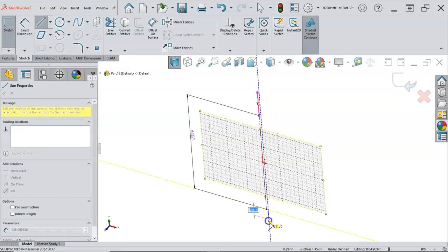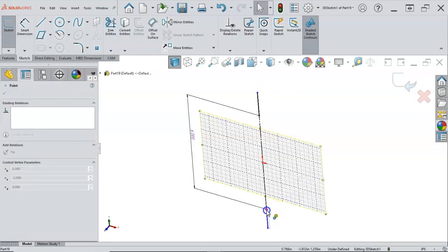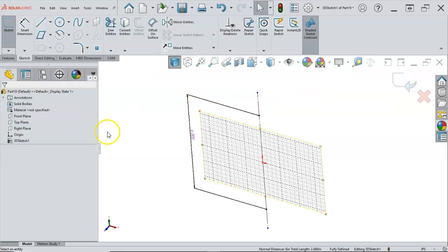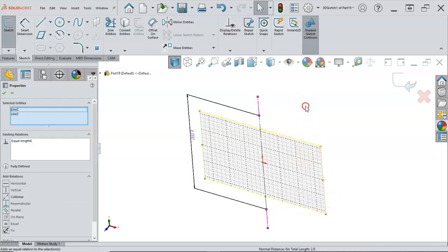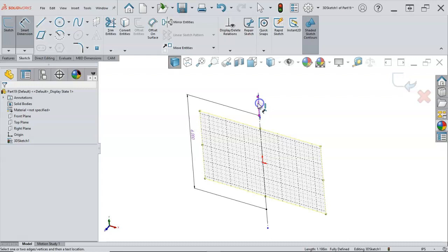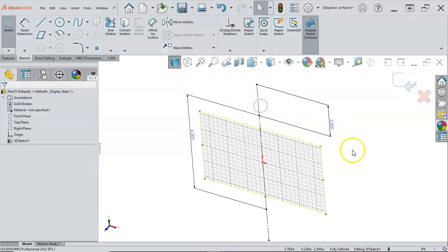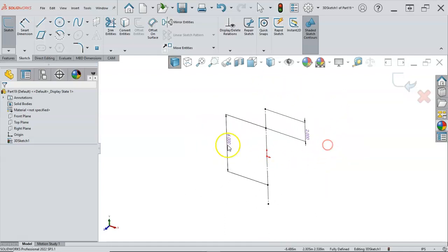All right, and then for the peak, we'll do pretty much the same thing. Placeholder, make sure that those are equal. Since I'm there, I'll go ahead and apply the construction geometry and then set to equal. And we'll put a dimension in place. All right, so that gives me the ability to stay in that angle so I can hold my perspective. The little used plane in the sketch tools: insert a plane into a 3D sketch.